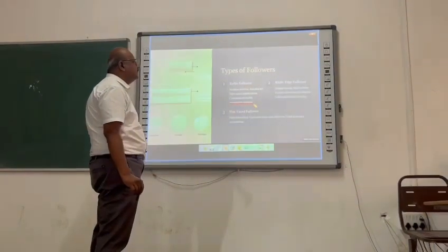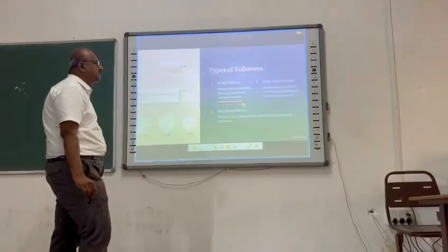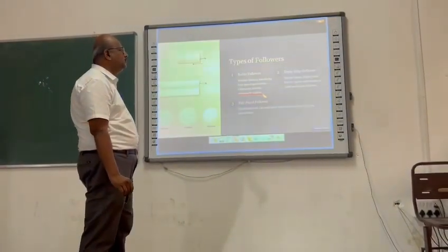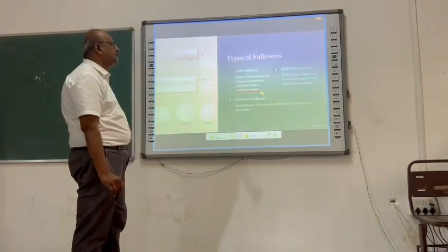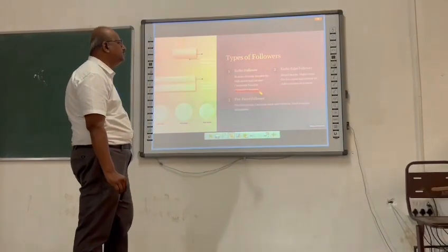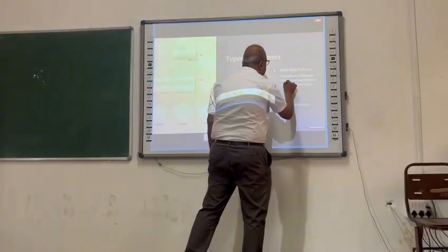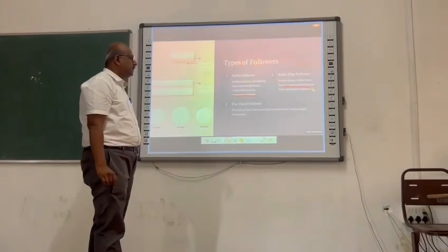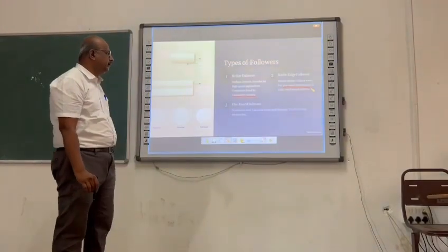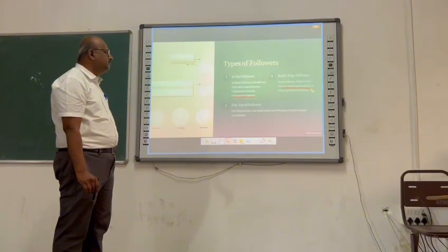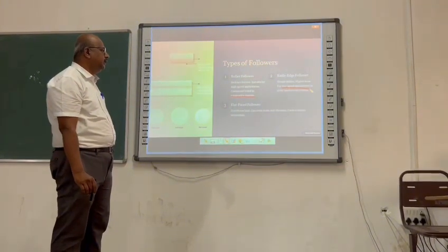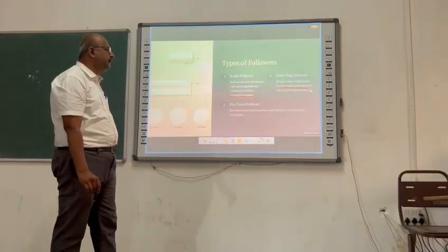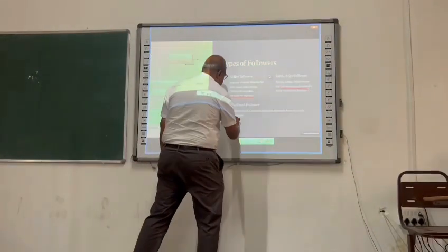The second one is the knife edge follower, which has a simple design and higher wear, and is used for low-speed applications in older mechanical systems. The last one is the flat-faced follower. It distributes load, can cause noise and vibration, and is used in simple automation.